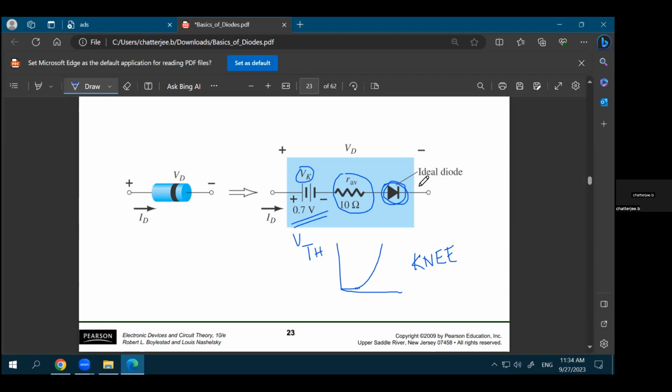I know where you're going, but if there is a DC difference between these two points, there will be a DC current. We haven't discussed what's inside the op-amp yet, but usually the op-amp is designed in a way that if you push this point and this point, there will not be a DC current flow from here to here, which means that DC point can happen. If there is a DC current flow, it's a wastage. There is a current flow through the device and you are not doing anything with that current. It's a wasted amount of current, and that's why op-amp designers will try to avoid that.